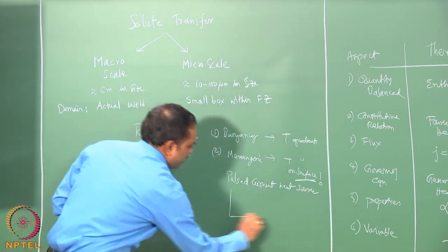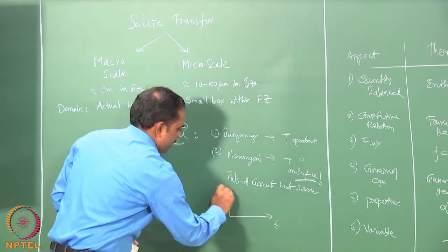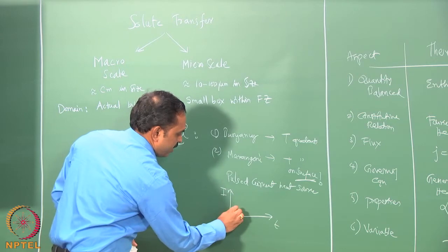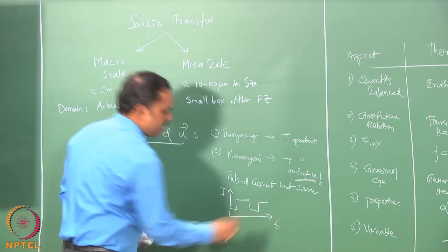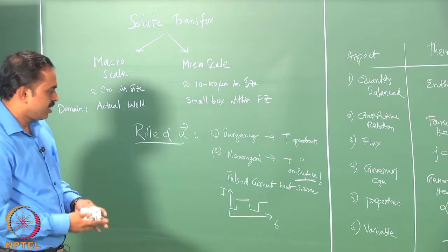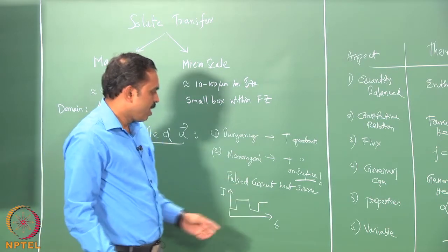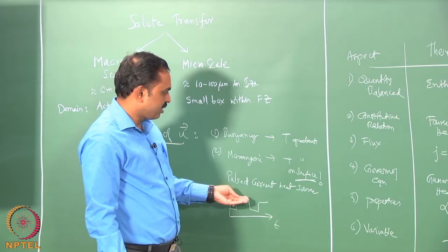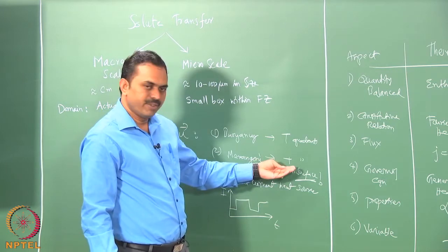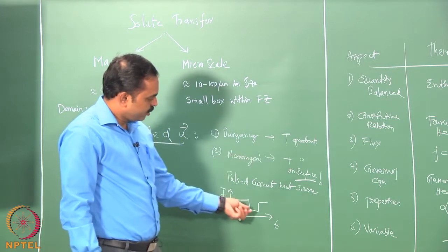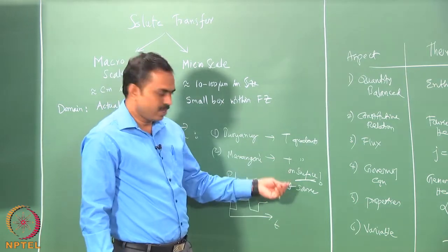What it implies is that as a function of time, the current is going to be taking shapes like that, and it means that for some duration the current is high and some duration is low. So, in the durations where the current is high, the maximum temperature achieved will be high, and in the duration when the current is low, the maximum temperature will be low.